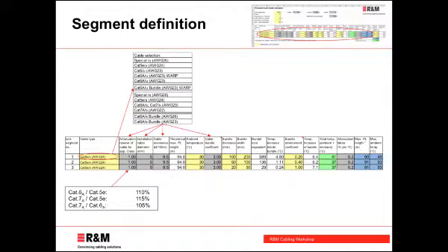The attenuation reserve is a factor that is included, because if you use a Category 6 or 6A cable instead of a Cat 5e cable, you obviously have lower attenuation. And this lower attenuation allows you to run a longer length of cable, of permanent link, and the factor from 6A to Cat 5 is 10%, or is whatever we have in here.